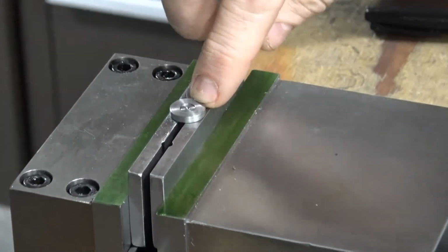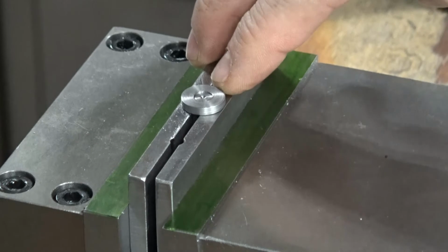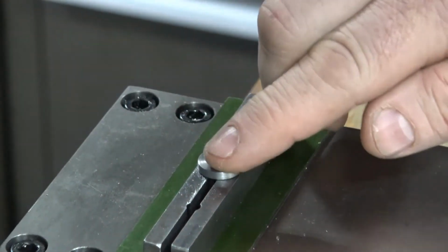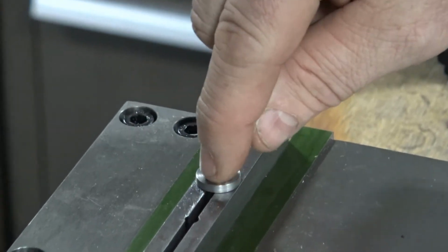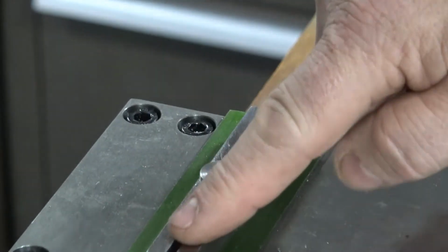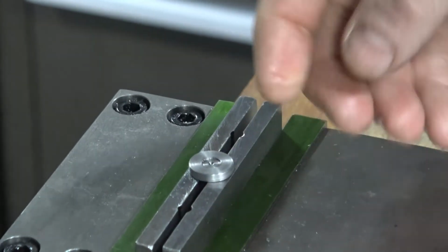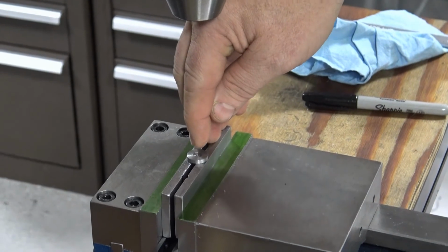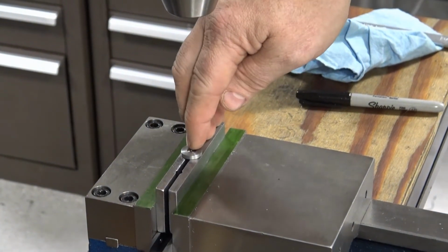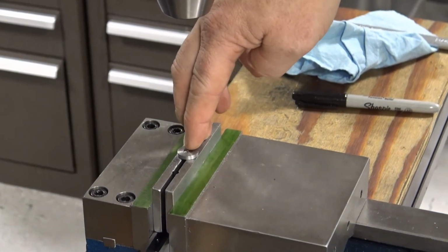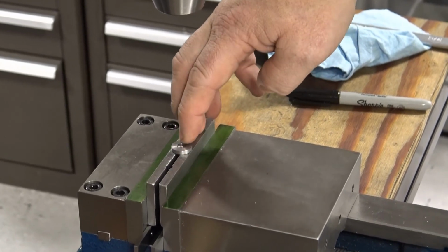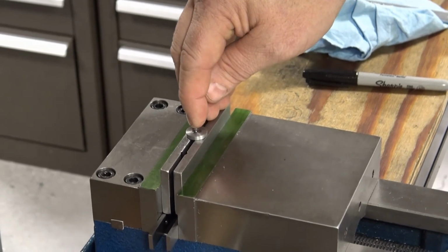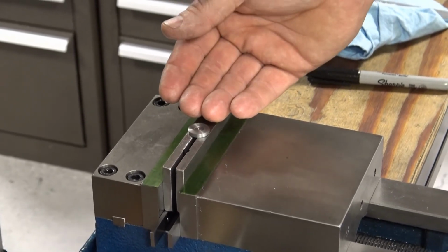There are times, and if I were going to machine this myself offline and not with students training underneath me, I may lift this cylinder or this disc up off the top of the jaws. Well, that causes a different issue. These two pieces are pressed together. So if while drilling I apply too much pressure on that 5/8 disc, I could easily dislodge that press fit and cause this piece to come off in two pieces.